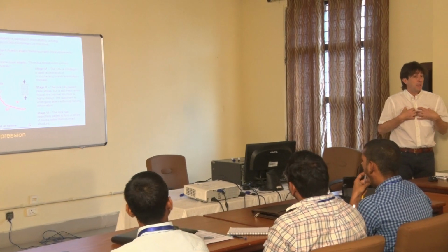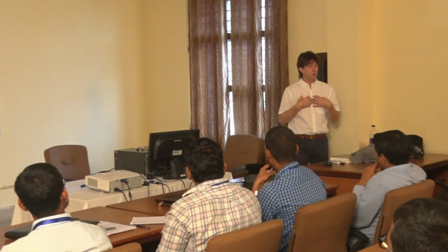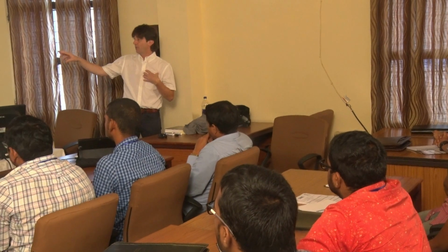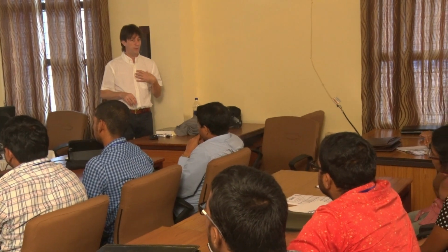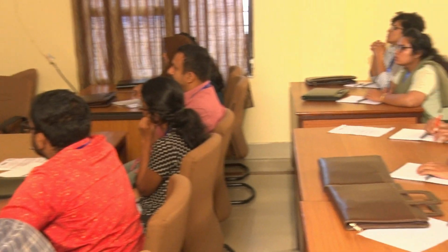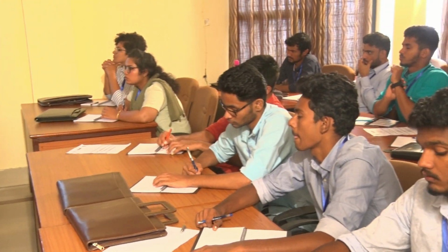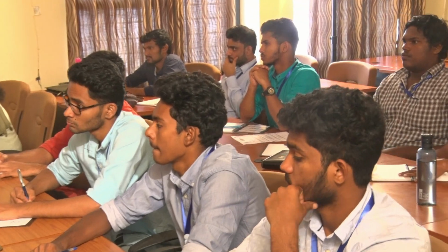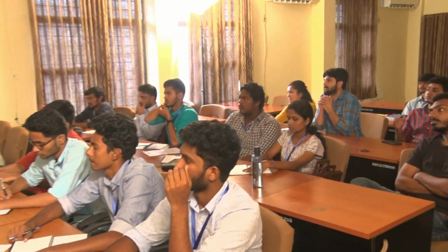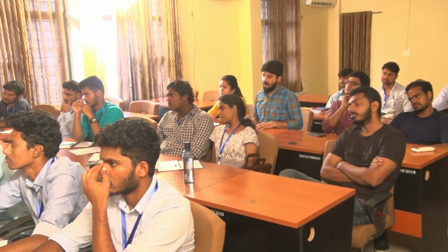And the reason is that each machine will have a different response that will actually be captured by that number one. Plus, how you set your sample, how you prepare your phases. Everything is that. There's so much uncertainty that it's pretty much impossible to actually get any reasonable interpretation of what number one could be. Number two is really the area, that section of the curve where the rock behaves linearly.